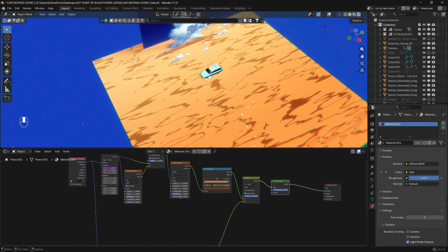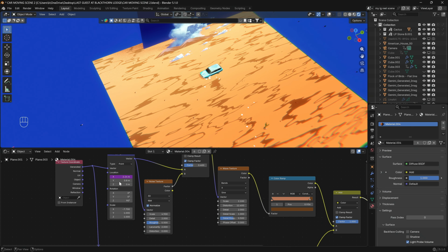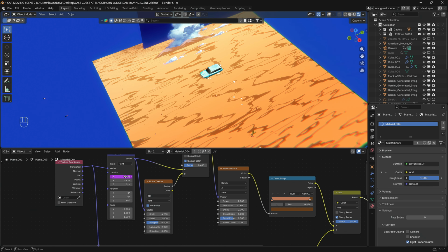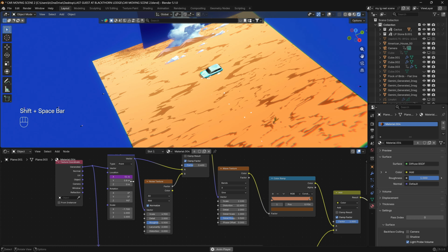And how I was able to animate it is by creating an offset driver on the x-axis. To do that, you just click on it, you type frame, and the driver is put in. Once you play your animation, it plays. But the reason why it doesn't play right now is because we used it in caps lock. So make sure that it's turned off and you're using small letters. So by the time you play it, it plays.